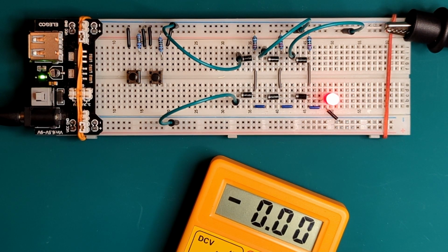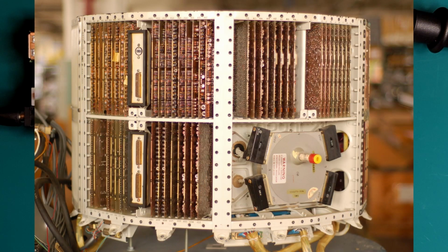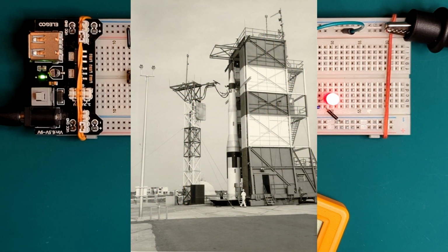In the end, this was not the gate we were looking for, but it's my closest approximation so far. This gate, called Diode-Resistor Logic, has been good enough in practice to build some real computers or parts of some real computers in the 50s. Given that they have some issues, it's not something you put to fly a nuclear missile, except that this is exactly what some of these diode logic computers did.